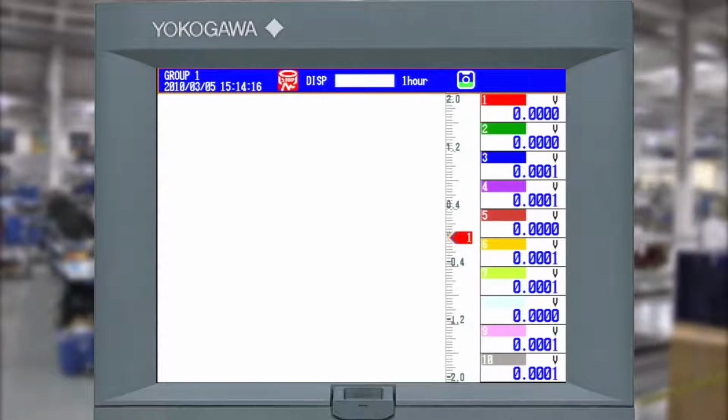Today I'm going to take you through configuring a DX Advanced or DAQStation with R4 firmware from scratch. I'm going to take you through how to set up a couple channels, how to put a network address in it, how to change it from default Celsius readings to Fahrenheit readings, and a couple other things along the way.